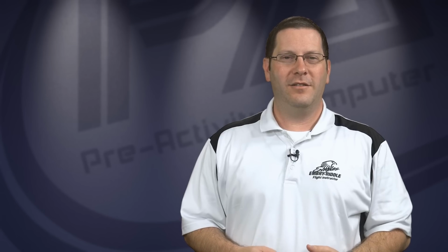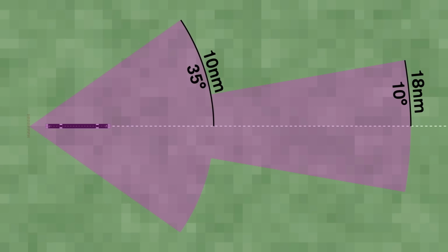Also similar to VORs, localizers have a service volume. A localizer's service volume is limited to within 18 nautical miles and 10 degrees of centerline, or within 10 nautical miles and 35 degrees of centerline. Outside of the service volume, you could receive erroneous indications or no signal at all.